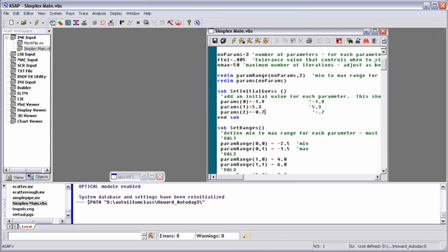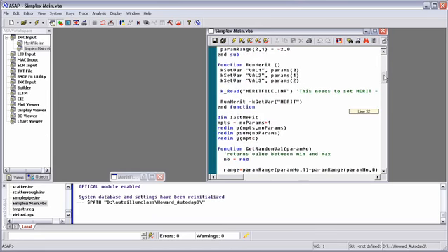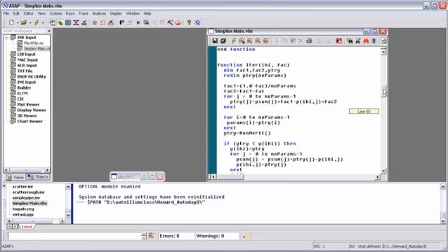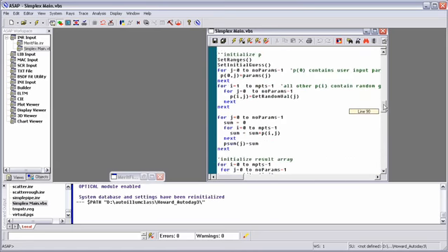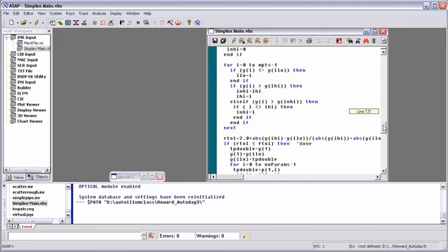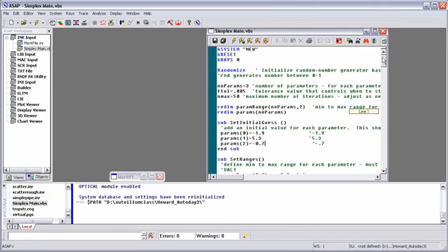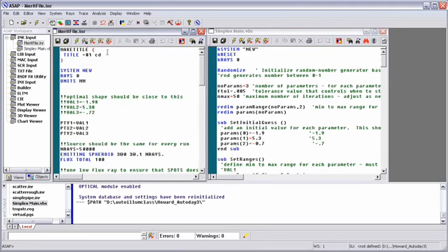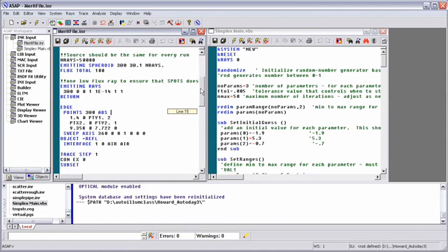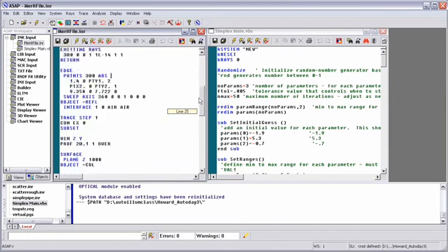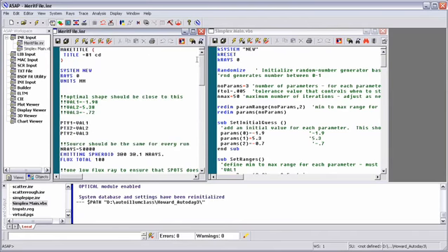For the illumination system then, we've actually written a VBScript file that contains a downhill-simplex method. If you're familiar with optimizations, the downhill-simplex is one that's commonly used for illumination. So the downhill-simplex code has been written into the VBScript file, and we can combine that with our ASAP file to do the analysis of the illumination system. And we're going to feed back the information from the analysis into our downhill-simplex, and the downhill-simplex is going to continue to run the ASAP analysis until we have optimized the system based on the criteria that we've given it.